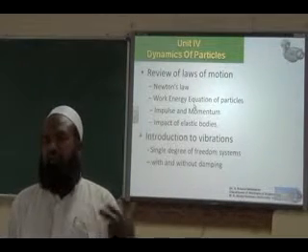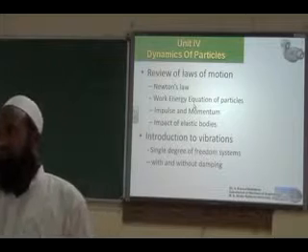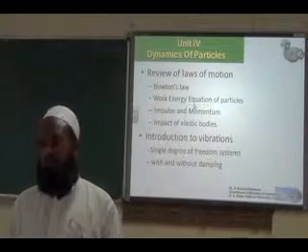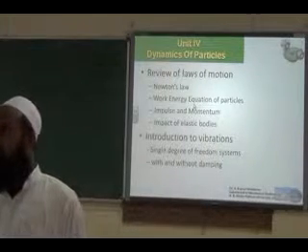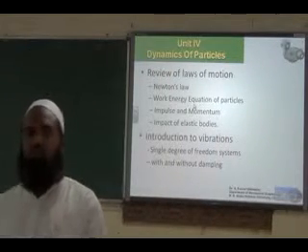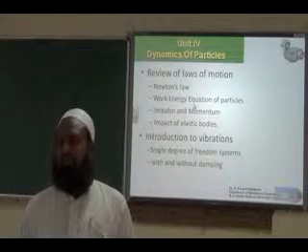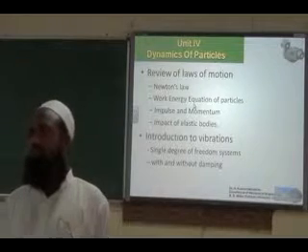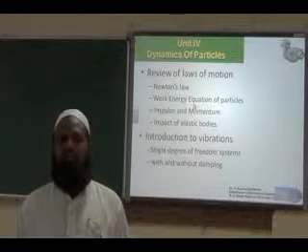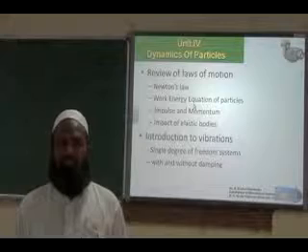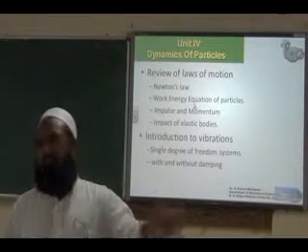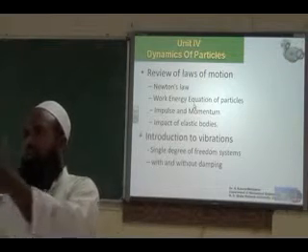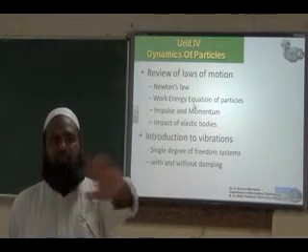As I told earlier, equilibrium can be static or dynamic. F will be 0 under two conditions. The first condition is that there is no movement at all. Velocity is 0, it is at rest. That condition is static equilibrium. What is the other condition? F will be 0 when velocity is constant. If velocity is 0, acceleration is 0. So in F equals ma, A will become 0. That is the first half, static equilibrium.